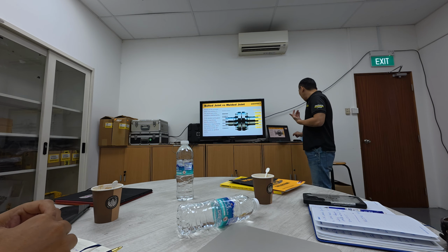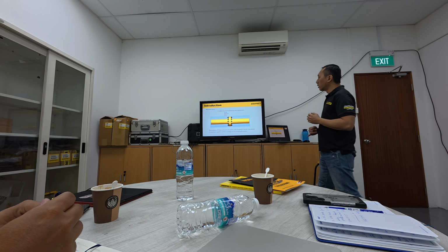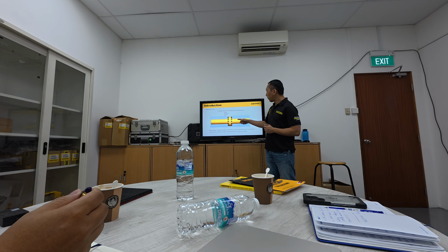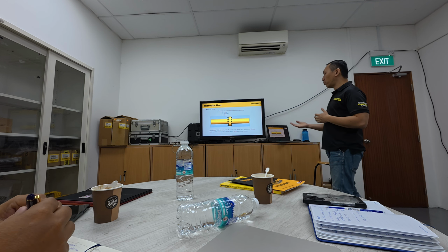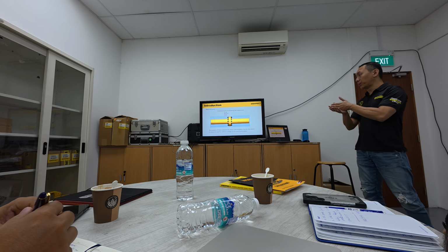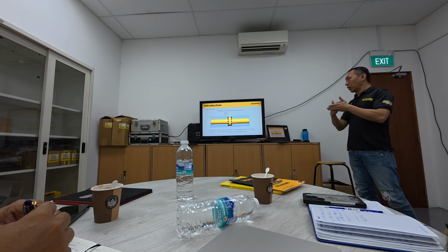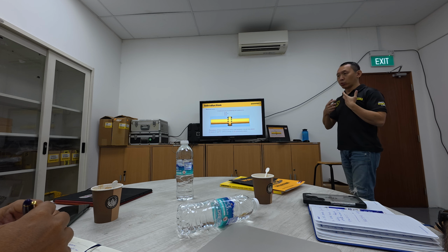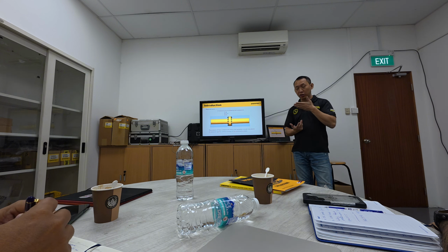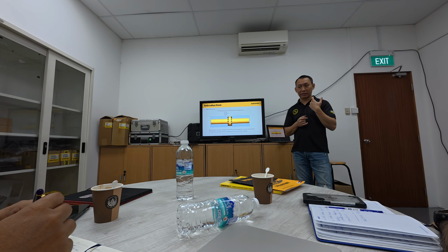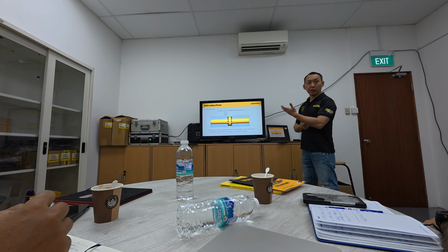So this is a bolted joint. The main components of a bolted joint are the flange, the fastener, and of course in between the gasket. This is very important. The purpose of these components, used correctly, is to join two pieces of pipeline together without any leak of the contained product. So if you see leaking, that most likely means the joint is not maintained. The joint needs to be maintained to ensure there's no leaking. Otherwise, it will be very disastrous, especially if there's pressurized material within the pipeline.